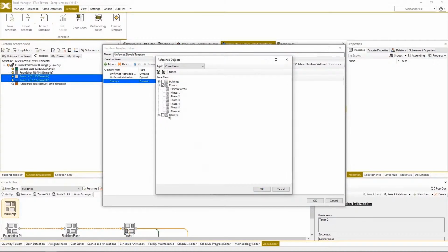So for every floor, whenever it's required, for instance in the building base, which is like 6 times bigger than the area of a single story on the towers, we're gonna divide this big area into 6 separate zones in order to optimize use of resources on our project, so that we can execute this big area in 6 separate phases using the same resources that could later be used in the area of towers when we start.